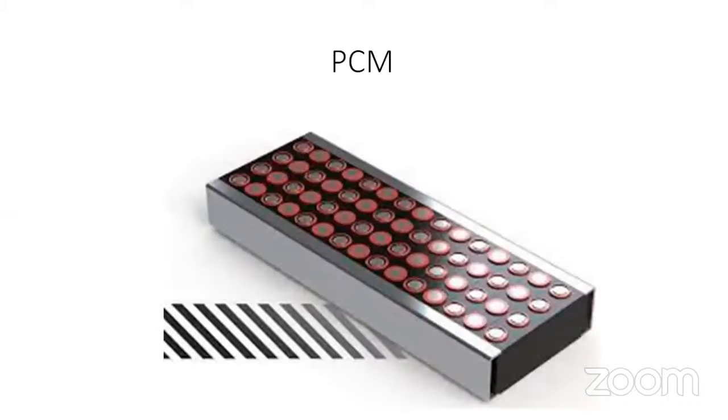Encapsulants are there, I told you. So in those gaps between these two cells, we fill the encapsulant. Encapsulants are dielectric and thermally insulative materials, which we use for potting into that, and that's why they are called potting material as well. Okay, so those all are encapsulants. Sometimes people use PCM material as well. PCM is called phase change material.